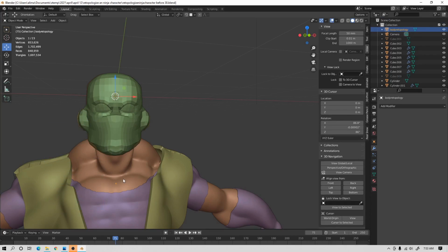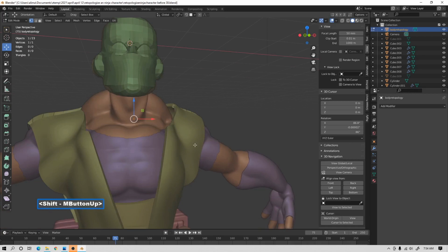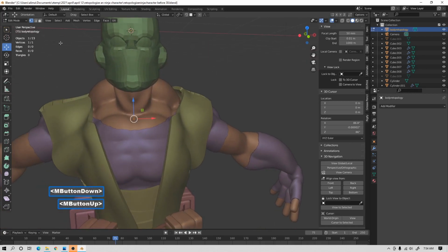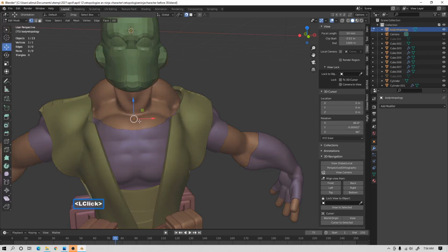Okay, what we're going to do now is go to the upper left, go to edit mode. I'm going to hold Shift as well as the middle mouse button to pan. I'm going to go back to the upper left, go to object mode, turn on snapping. Or I went to the middle upper screen, upper left edit mode. We have the one vertex selected. I clicked off just to make sure, so I left clicked on nothingness to deselect. I'm pressing A to select everything now.